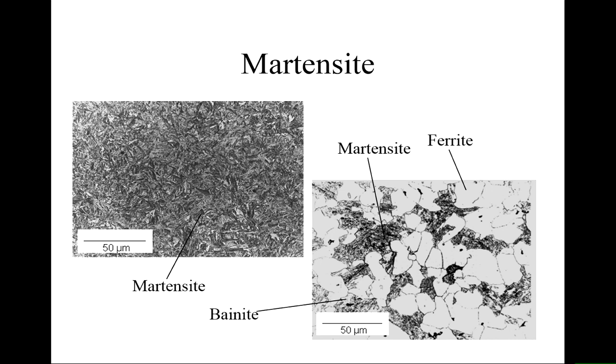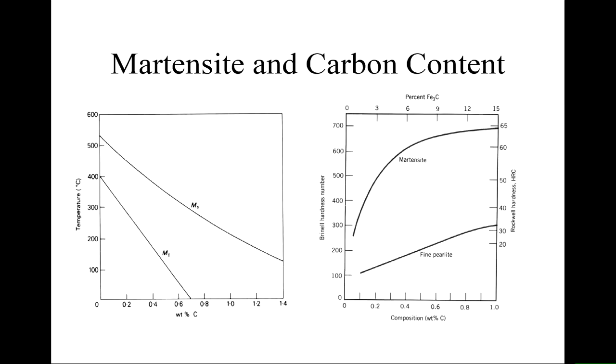So it's perfectly possible to have the same material show two totally different microstructures just depending on cooling rate, and it can have really brittle phases and really ductile phases mixed. So as far as we're concerned, what we want to do is get rid of as much of the martensite as possible. So we need to know a little bit about what the conditions are for making martensite.